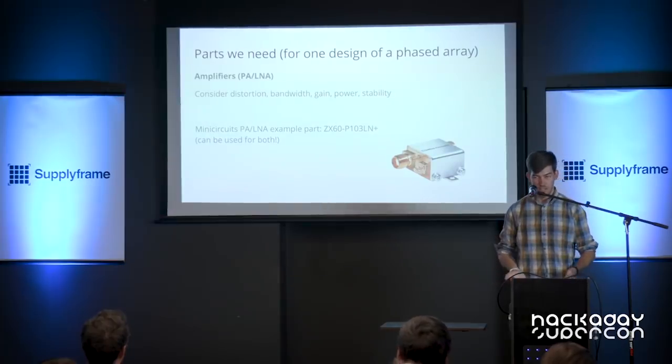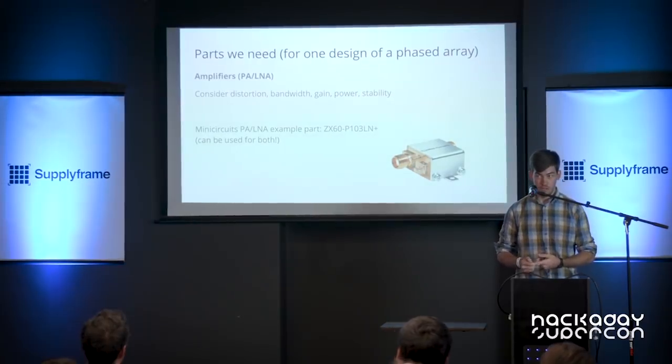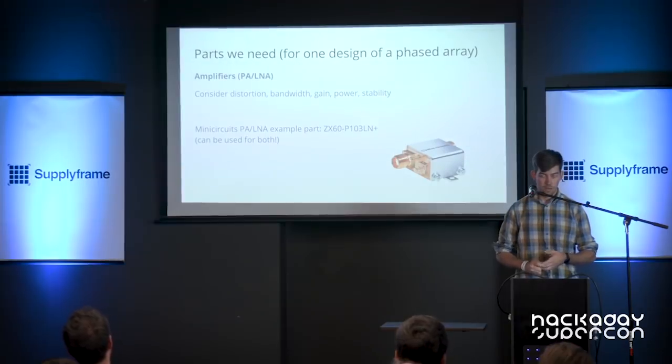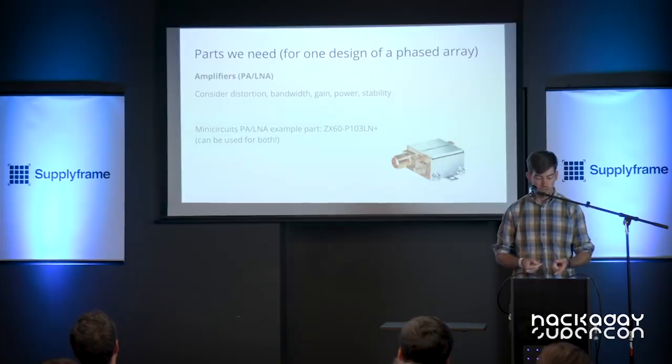Amplifiers, obviously there's a lot of stuff you need to take into account depending on what you want to do. If you're trying to send information, you want to make sure it's not going to be too distorted by the time it gets to your antennas. You also want to make sure that you have enough bandwidth, that if your gain is super high, you can have stability problems. This amplifier that I've listed here, for many circuits, for hobby purposes, can be used as both an LNA and a PA.